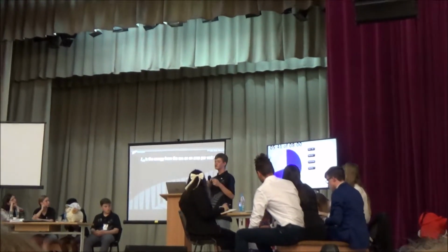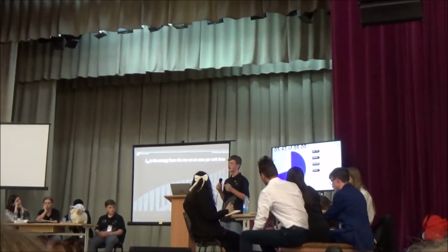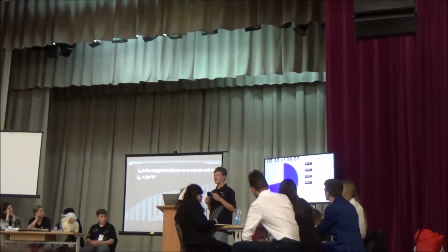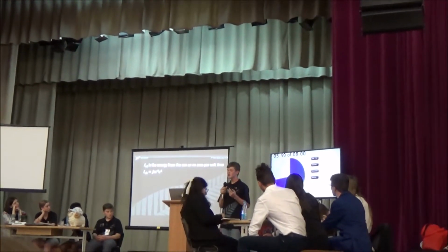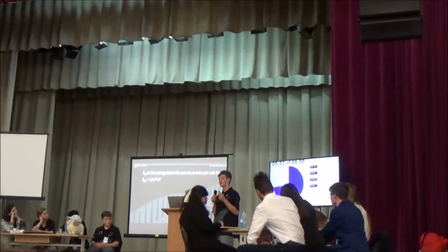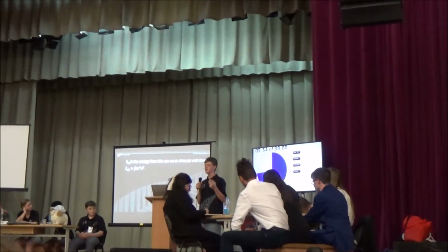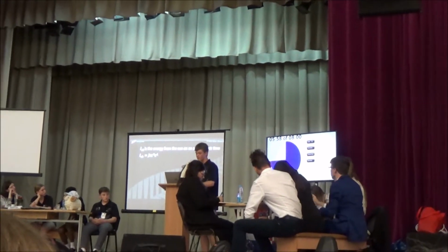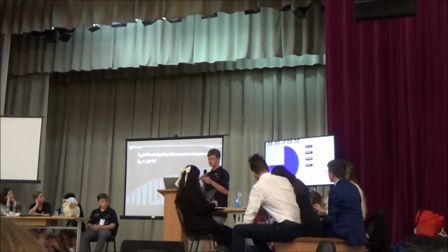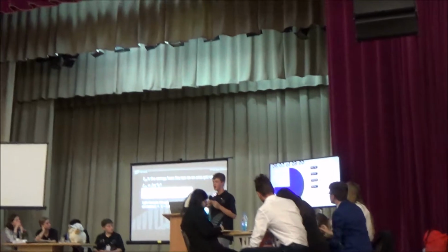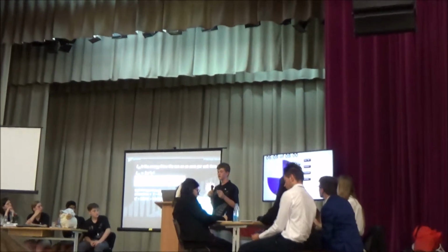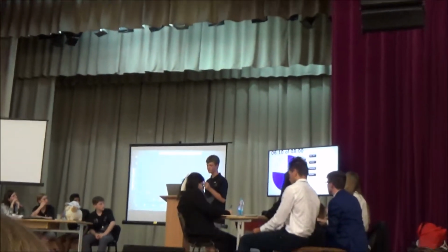So insolation is the energy input per square metre per second, and its units given is this. And as I have stated, the time of day has an effect on how much sunlight you get. This is normally given as a 30% loss per 1 AM. AM is the thickness of the atmosphere which the sunlight is travelling through, and it varies based off the time of day. And so the relationship for that is given as this. And the insolation before the atmosphere's effect is called the solar constant. So we're using this as a counting value for my heat flux.